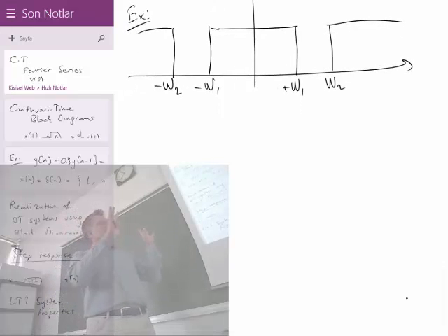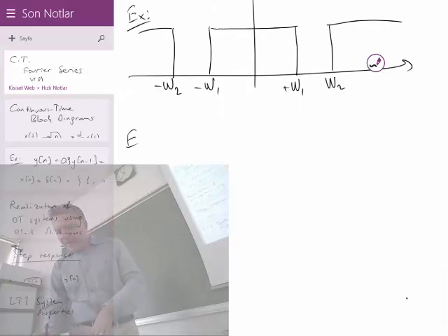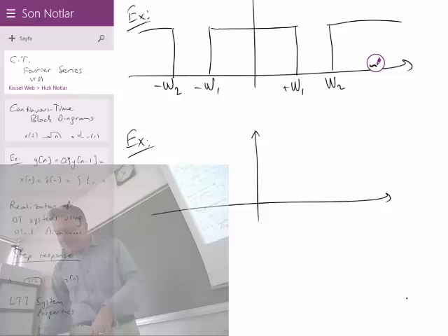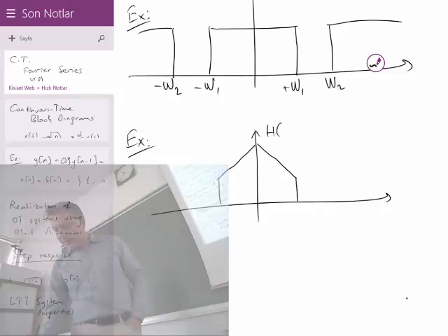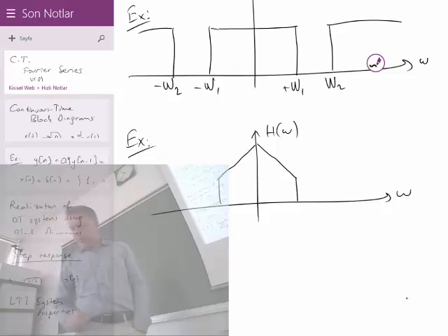It may also be useful. These are very standard filters, but of course we may have other filter types, quite arbitrary filters as well. For example, what is this? It is again sort of a low pass filter because it doesn't pass high frequencies, but in the low range it is distorting the signal a little bit. The lower the frequency is, meaning the nearer to the center, the more it is amplified. So it is somehow distorting.